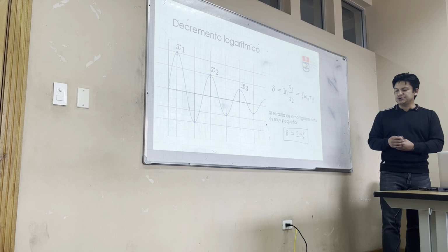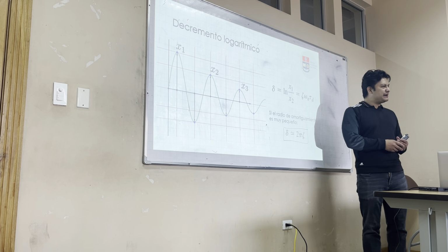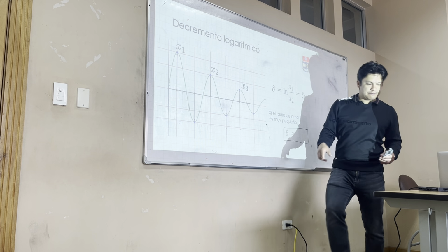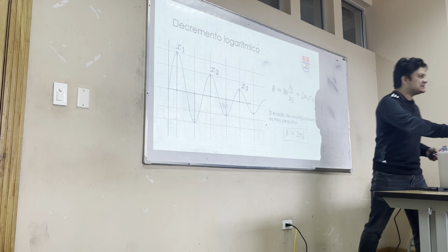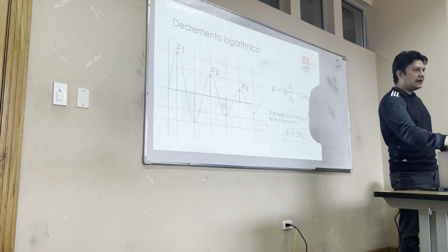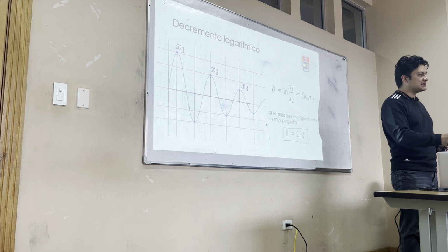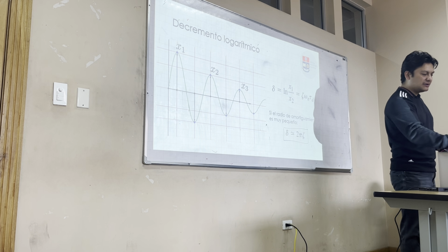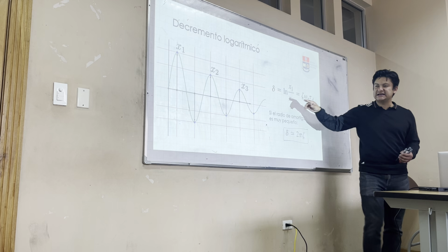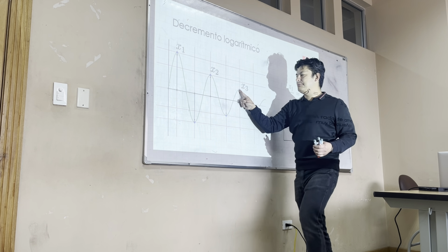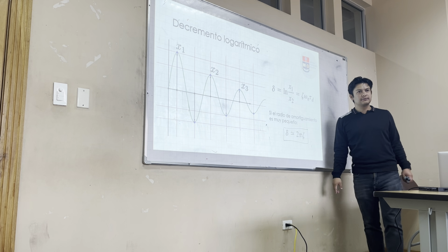What you actually do is perform an experiment in a system and get this curve. For example, you hit the system, you put an accelerometer here, you move this, and you record the data. For example, this starts vibrating, doesn't it? It vibrates, you put an accelerometer, you record the data, and then you know information about the amplitude of each of these points.